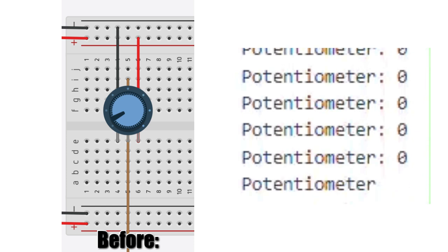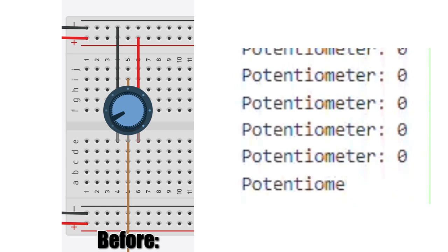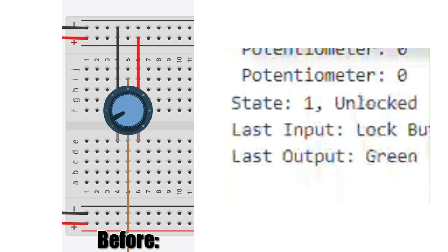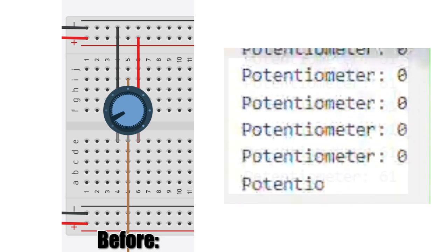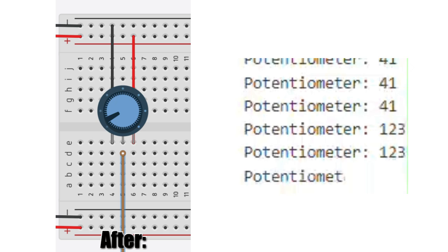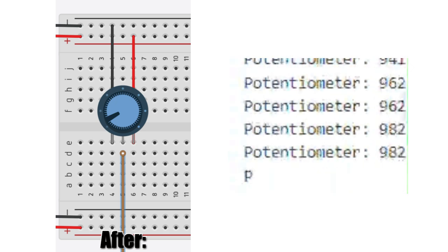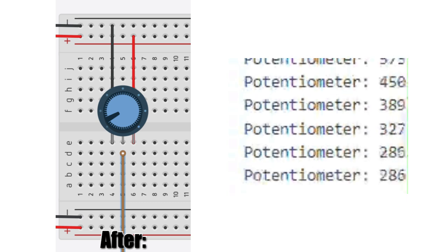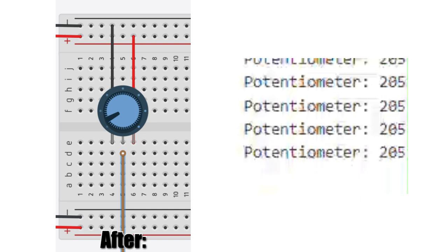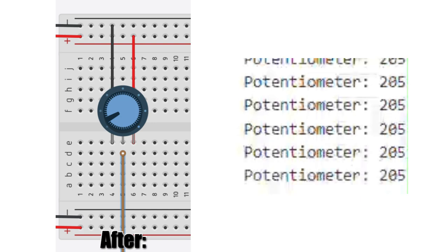Before solving this problem, we could not understand why our serial output was only printing a value of 0, which we later determined to be due to incorrect wiring of the wiper, which did not send any signal to the board. We diagnosed this issue by realizing that a continual 0 value meant the potentiometer could not be correctly connected and thus made a hardware issue probable. This was then confirmed and rectified. We amended this, and this allowed our LED to output light and let our program function.